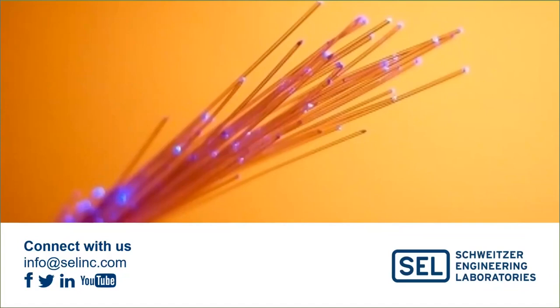Another difference between Ethernet and serial is that on a serial connection, remember we talked about how we can provide that IRIG signal over the serial cable. That's one thing you can do there, whereas with Ethernet, the time synchronization methods are NTP or PTP. So when you ask whether Ethernet or serial is preferred, it really is one of those answers where it depends, and you need to weigh the pros and cons of each. I'm going to follow up with you on that and see if we can talk about that some more.